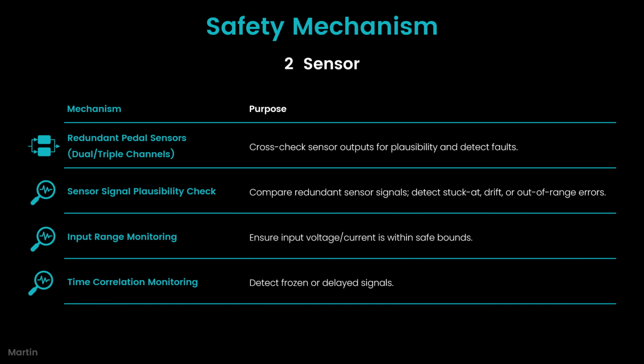At the sensor level, safety mechanisms incorporate multiple strategies such as plausibility checks to validate the consistency of sensor readings, continuous signal range monitoring to ensure values remain within expected thresholds, and built-in redundancy to provide backup measurements. These measures work together to detect potential failures, signal degradation, or gradual drift over time, thereby maintaining data integrity and supporting reliable system performance.